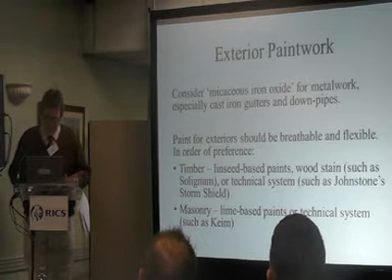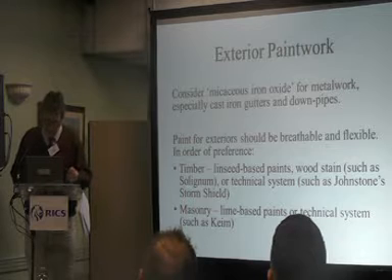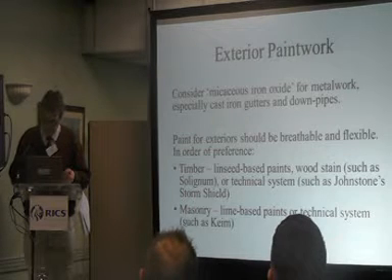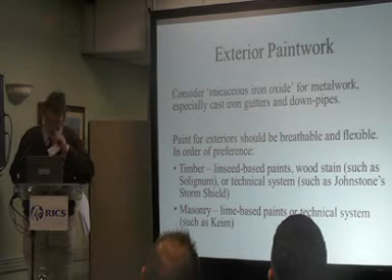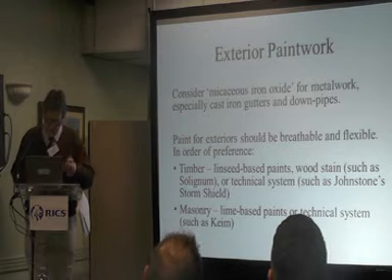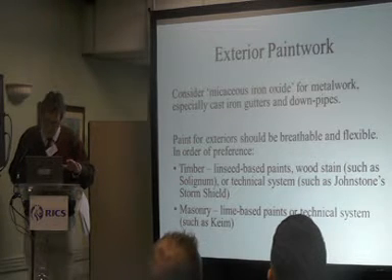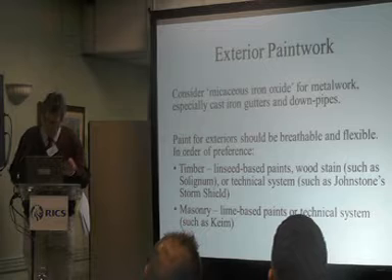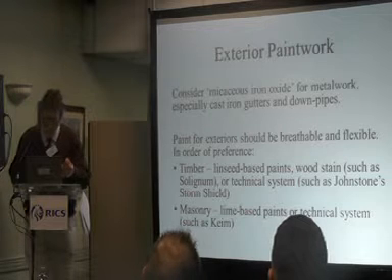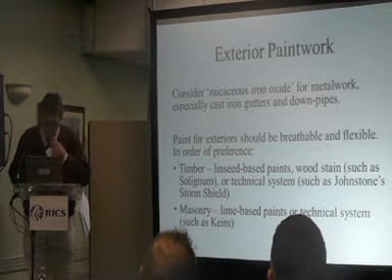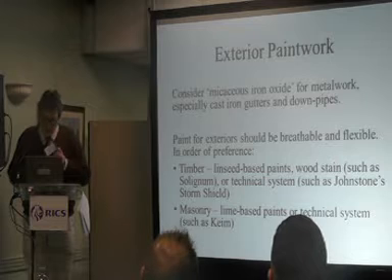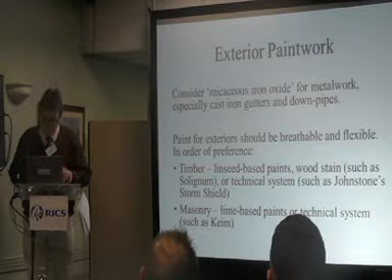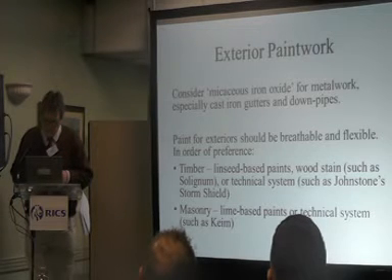For timber, go right back to linseed-based paints. I'm not here advocating white lead. In some circumstances I might, but for today I'm going to say linseed-based paints are fantastic. Available, a lot of them are Scandinavian. Wood stains, Solignum and others, not a bad second.